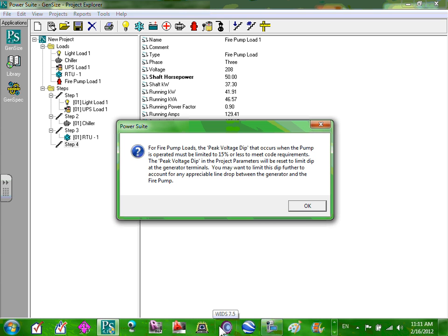When I do these though, however, I always want to have it in my head: what's the worst case that could happen? That's a great question. We want to set it up to where our biggest load might be starting last. Everything else is on and running, and we put the biggest load on last. Why? If it's going to take a lot to start that biggest load, and our generator's picked because it is last, we got it covered, right?